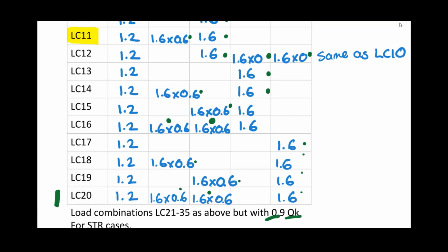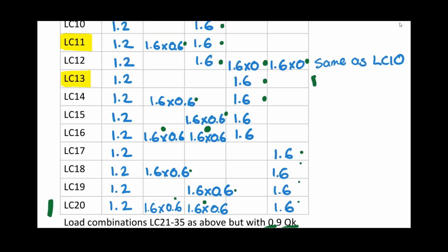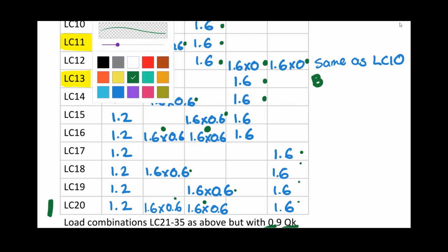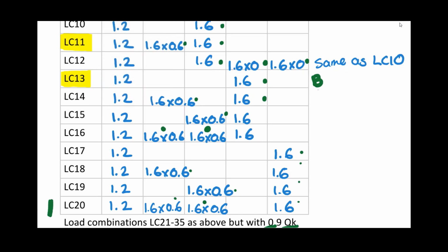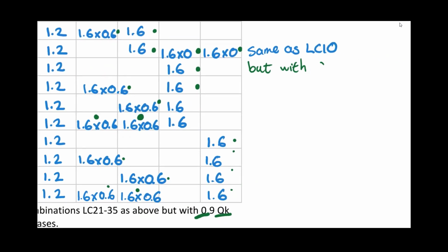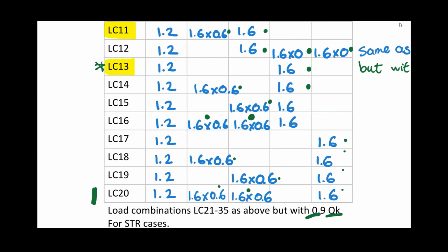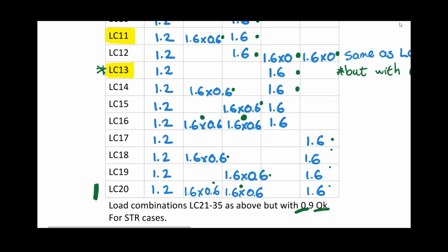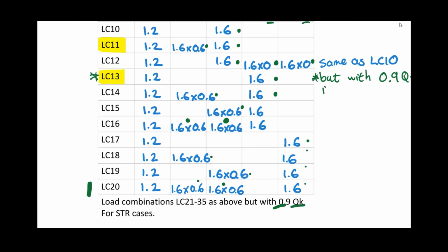Then potentially load combination 13, but if this is a suction load, we would want 0.9 uplift, but with 0.9 QK. This is a very possible one if uplift.